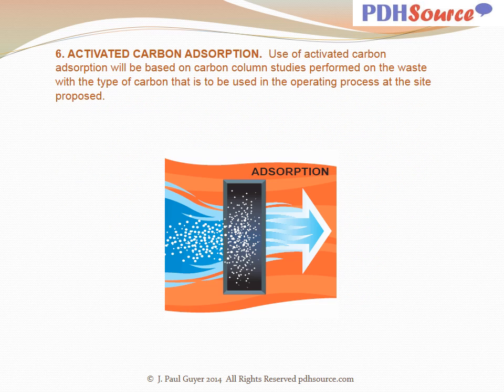The next methodology of advanced wastewater treatment is activated carbon adsorption. Use of activated carbon adsorption will be based on carbon column studies performed on the waste with the type of carbon that is to be used in the operating process at the site proposed.